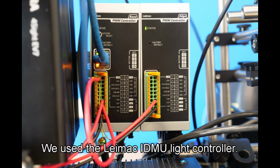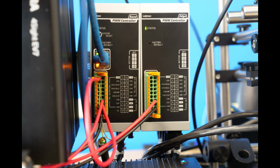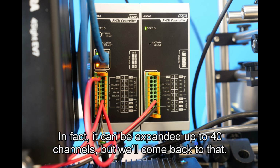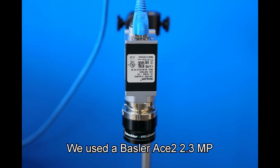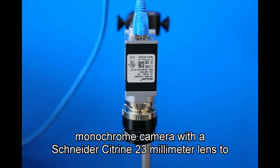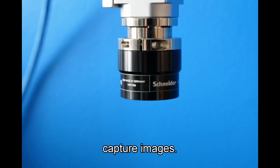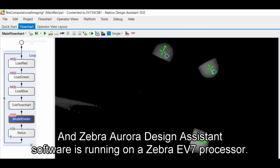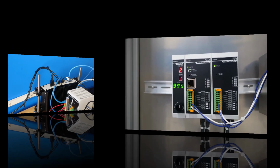We used the LAMAC IDMU light controller. We happen to use the 8-channel model, but it is also available with 4 channels. In fact, it can be expanded up to 40 channels, but we'll come back to that. We used a Basler ace 2 2.3 megapixel monochrome camera with a Schneider Citrine 23mm lens to capture images. And Zebra Aurora Design Assistant software is running on a Zebra EV7 processor.